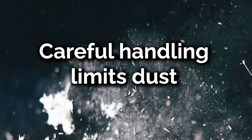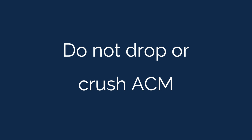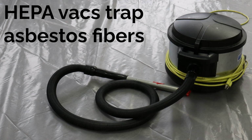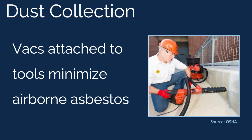Careful handling of ACM helps limit the production of dust. Limit abrasion by power tools, and do not drop or crush ACM. Vacuums with HEPA filters trap asbestos fibers. HEPA vacs attached to drills, sanders, and saws minimize airborne asbestos.